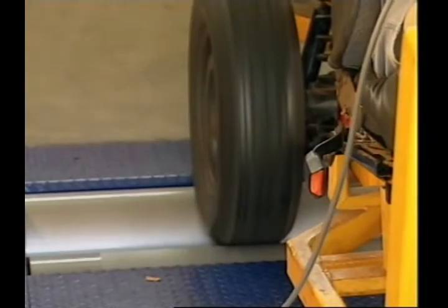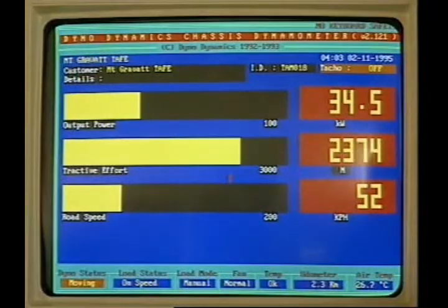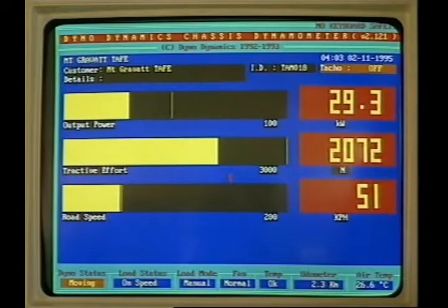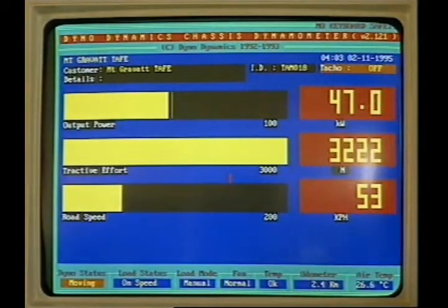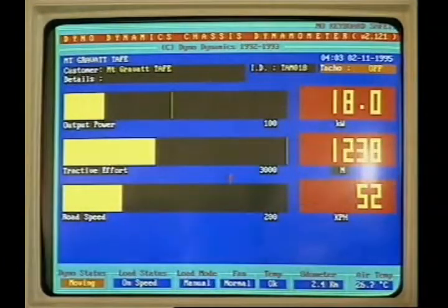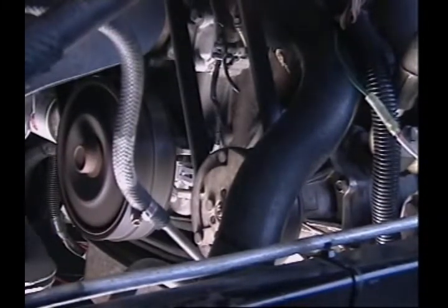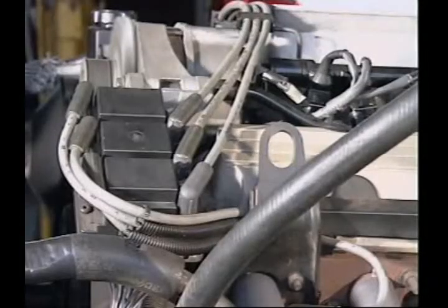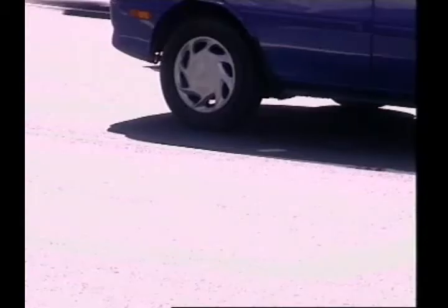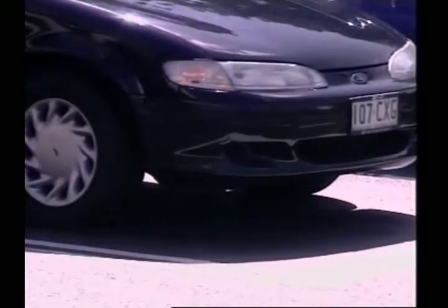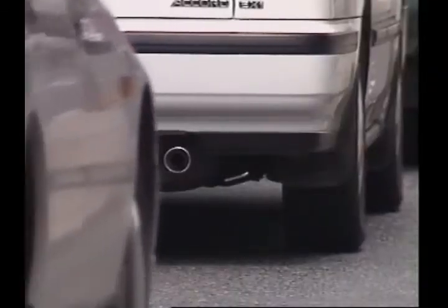Settings are made for various operating conditions according to fuel consumption, engine torque, exhaust emissions, knocking tendency and drivability. That means, for example, that starting ability can be improved by making timing during cranking depend on cranking speed. Timing at low idle speeds can be set for low emissions, smoothness and fuel economy.